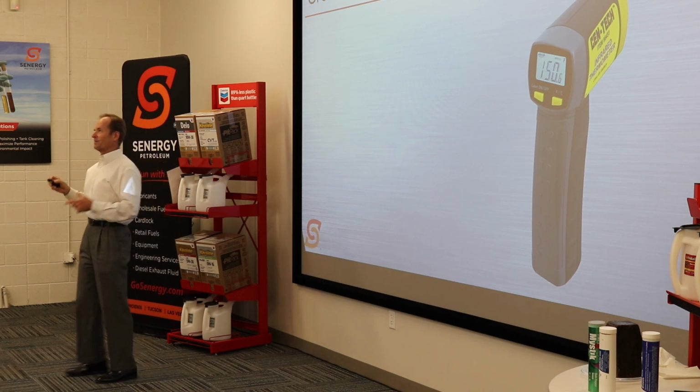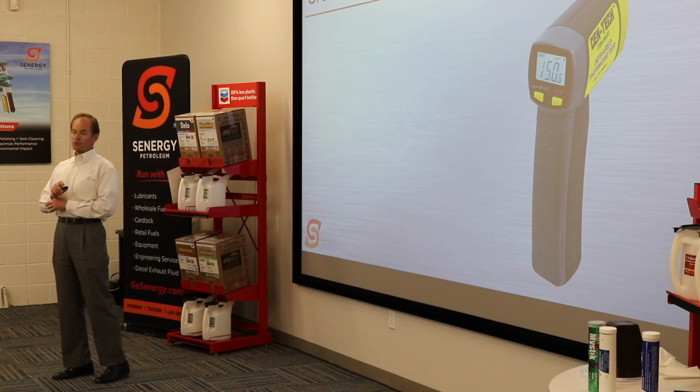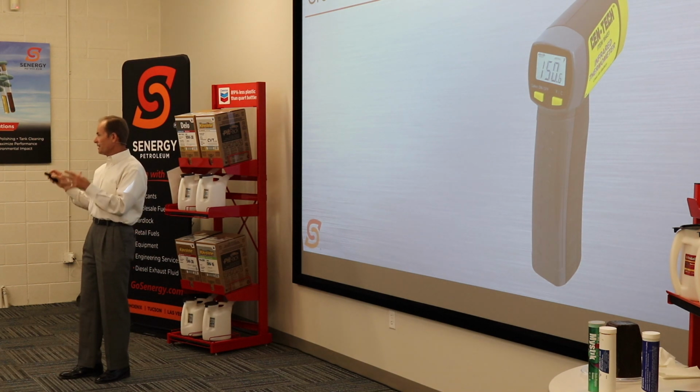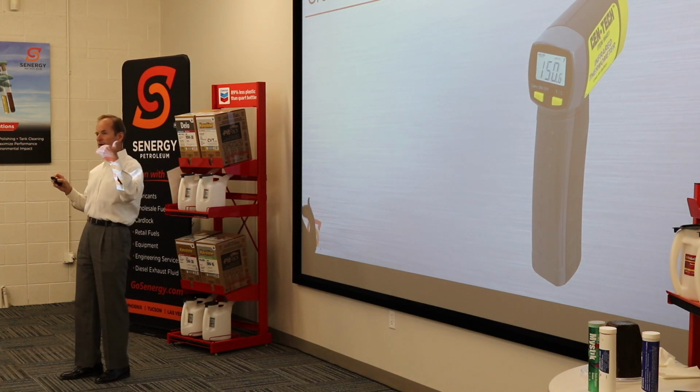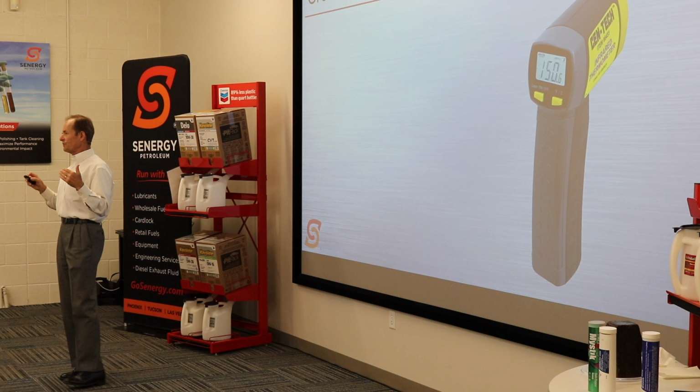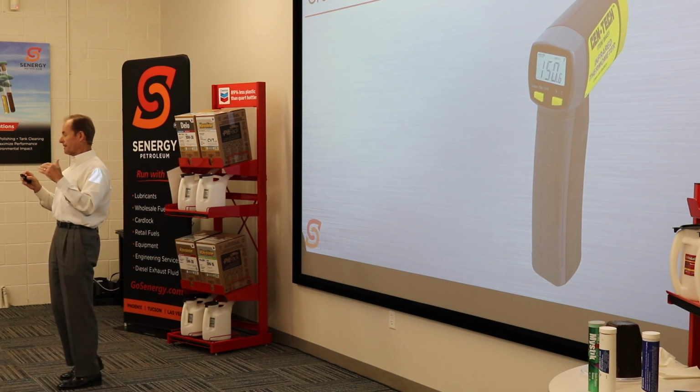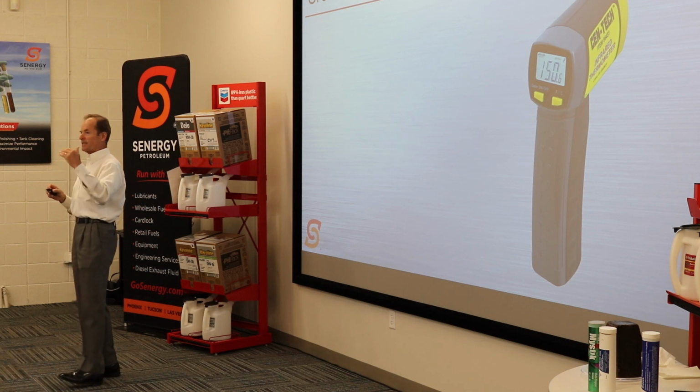But basically, what you're doing when you complex these soaps is you're building a better sponge. You're improving upon the sponge, and in most cases with these complex soaps, you've enhanced the dropping point. So the high temperature performance is getting even higher than its base soap. So a calcium complex grease has a dropping point and a high temperature performance much better than a calcium grease.